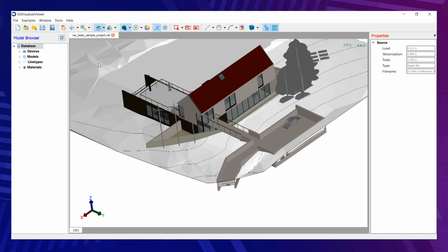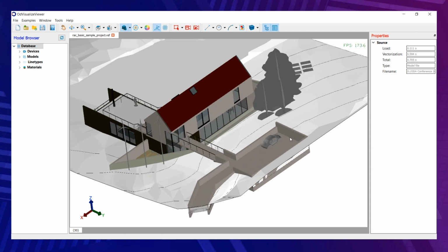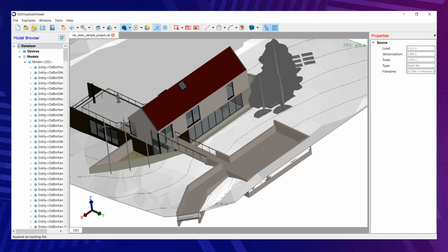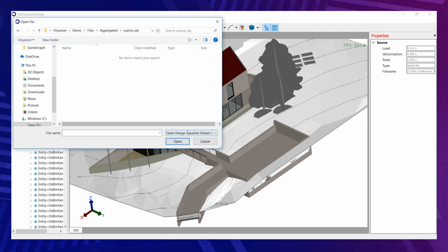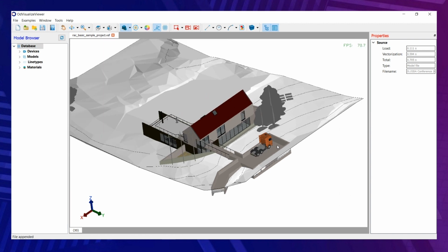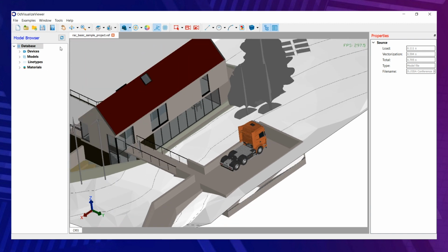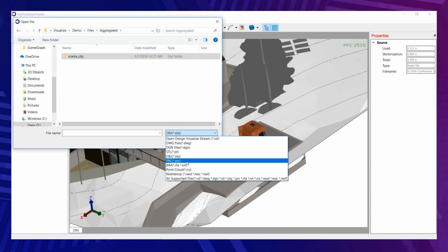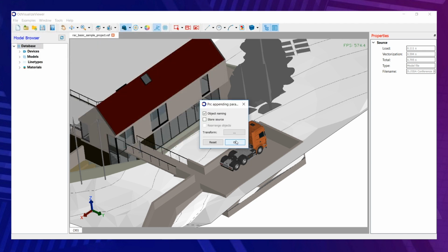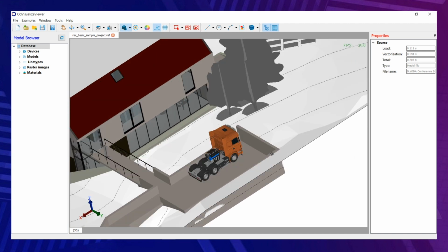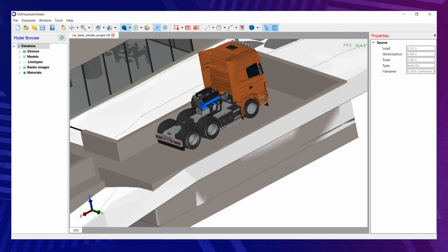First of all, we will remove this car and substitute it with the truck from the OBJ file. It is important to know that here it is necessary to use an additional transform matrix, because we should scale, translate, and rotate the data from different files to the same size, same position, and same orientation. So now is the final stage. We will add the PRC engine to the back of this truck. Now it's possible to see the result: how it's possible to merge data from different formats in one cache and in one view.